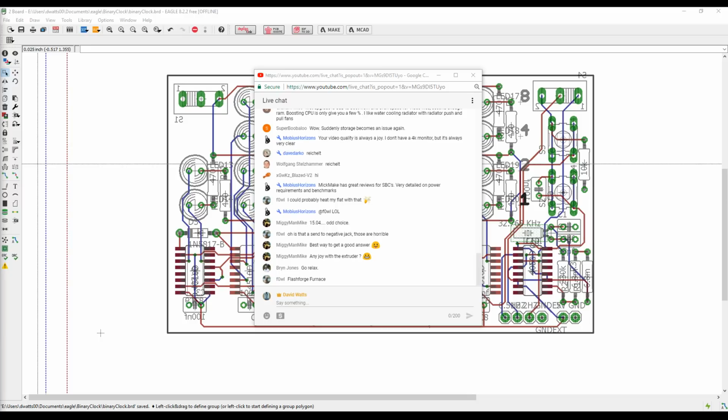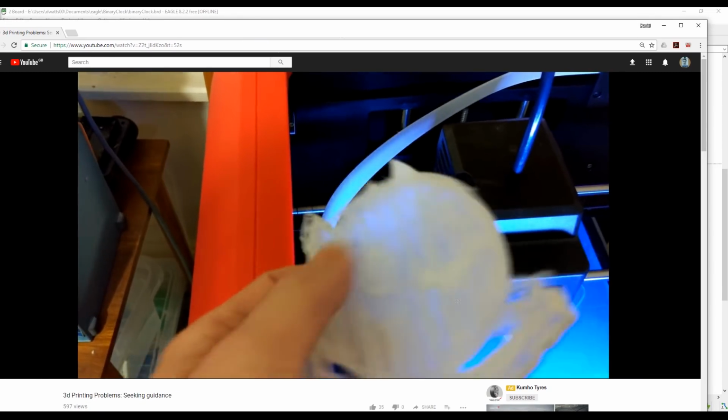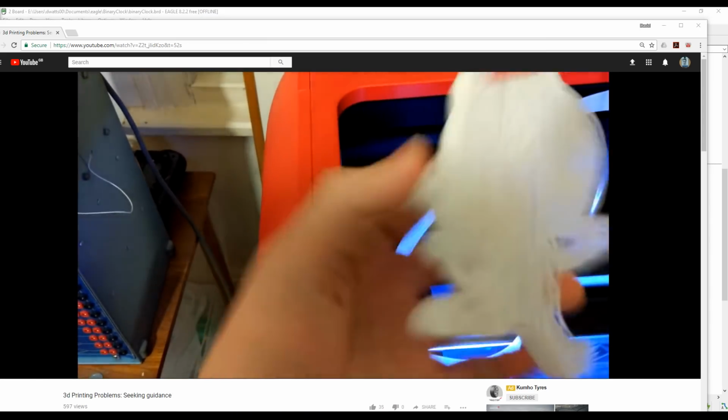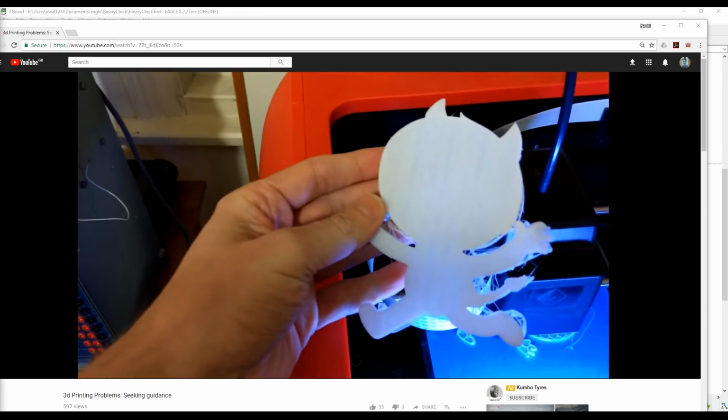So first of all, I tried leveling, because honestly, there's so many times when leveling has been the primary cause of my layers not working correctly, or the infill not sticking properly. It might be that the Z level is too high. I'll just put that there. Oh, and then I want that, not that. Oh no, where did the chat thing go? Hang on a minute. There.